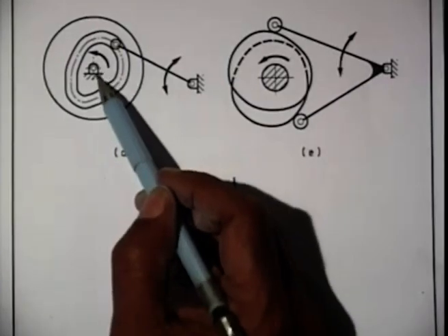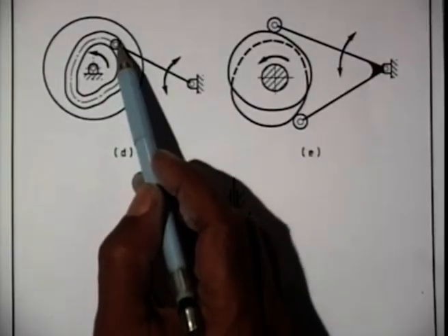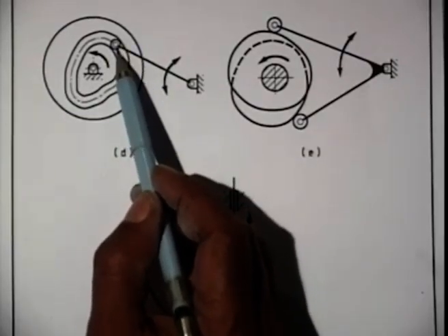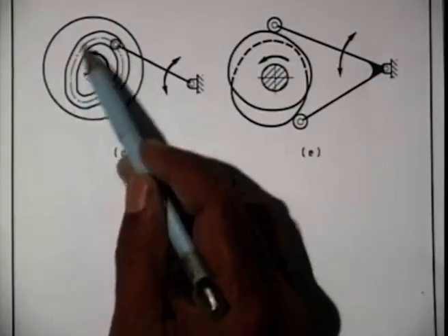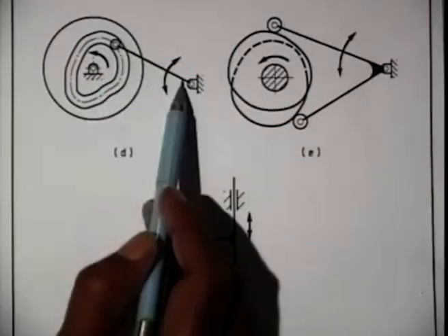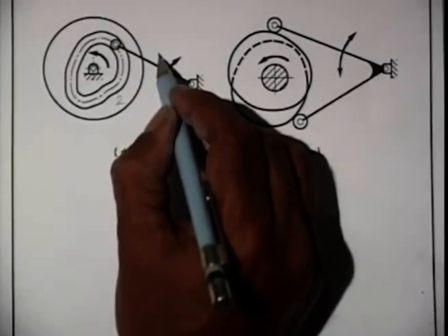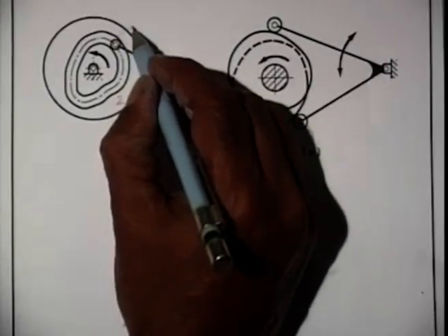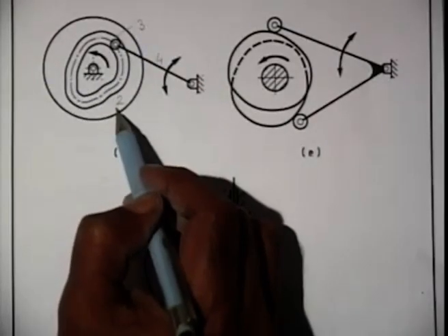In this diagram, as we have shown, no spring is necessary because the roller follower is placed in a groove. The shape of the groove is nothing but the shape of the cam, which will dictate the type of angular motion that this follower will have. So this is the cam and this is the follower, and this roller 3 has been placed inside a groove in this body 2.